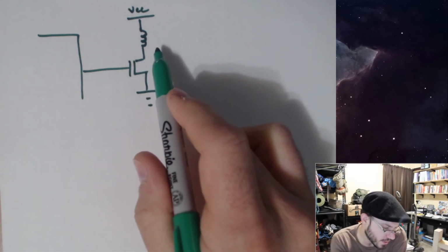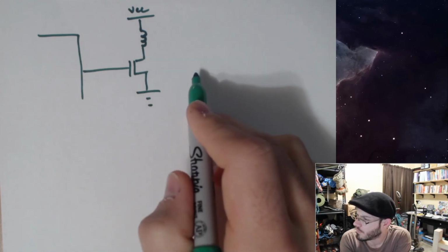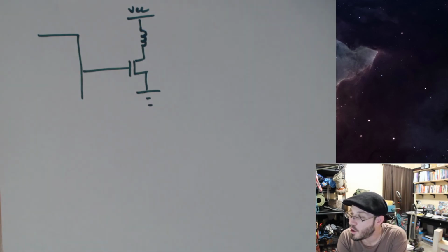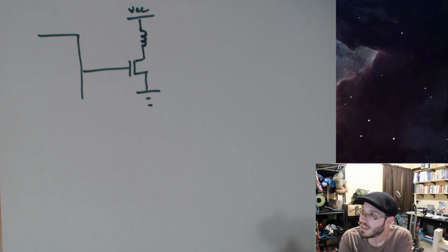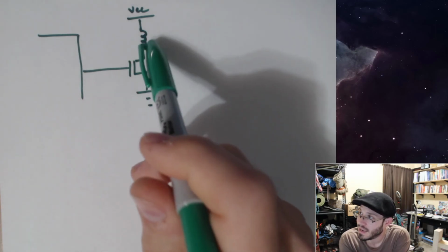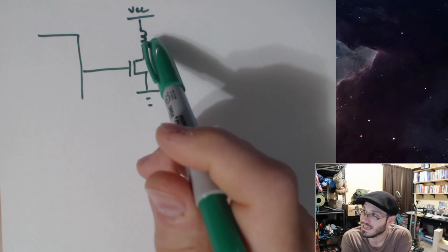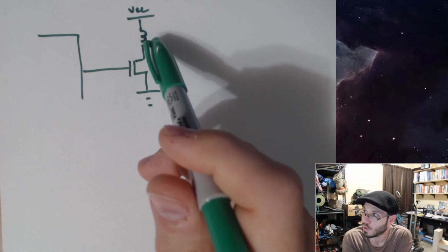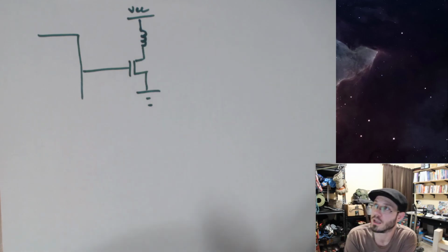Well, what happens when we go from on to off? No. The motor won't run backwards because the current is just decreasing. The collapsing magnetic field of that inductance is not going to cause the motor to turn.